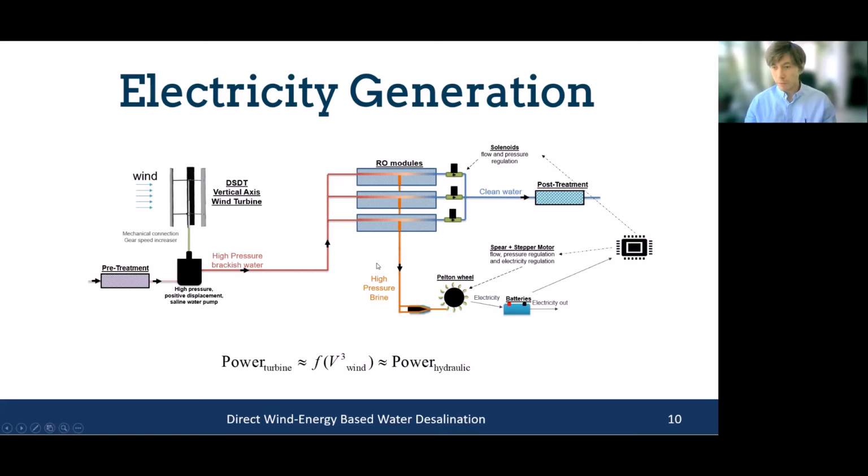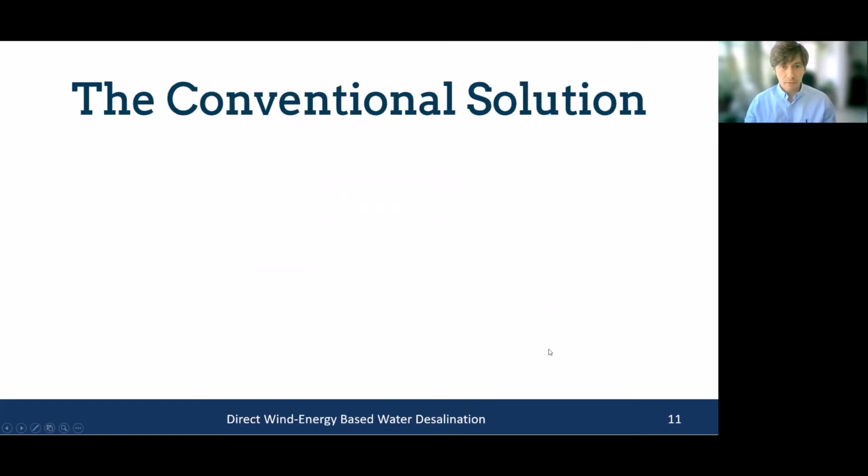So we said, maybe we're going to use a deep reinforcement learning-based controller. Why should we work with a deep reinforcement learning-based controller? This is because the system always needs to adapt. With time, the aquifer becomes more saline, and the pressure needs to rise. And this controller can compensate a bit. And maybe one of the modules wears off, or the pump or the Pelton wheel. So the system can always change a bit, and the controller can always adapt without the need for fine-tuning by a specialist. And this is our next step in the research.